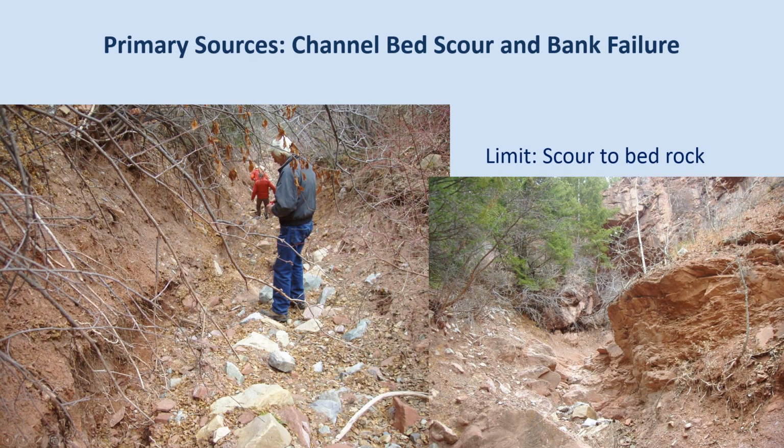And in this case, I think we were estimating that there was about 1 meter of potential scour of debris off the channel bottom, but it would result in additional sediment loading of the banks here, and maybe even a small hill slope failure. But what identifies the limitation here is that there's quite a bit of vegetation, where the root system is supporting the hill slope itself.